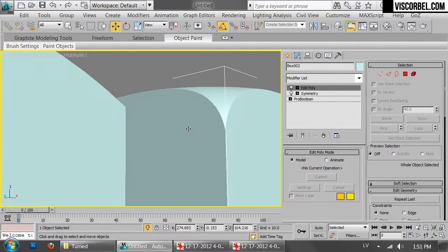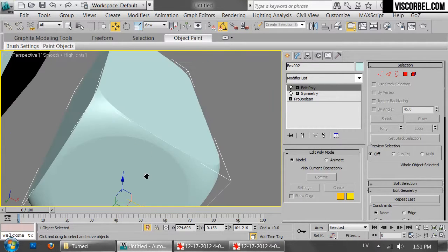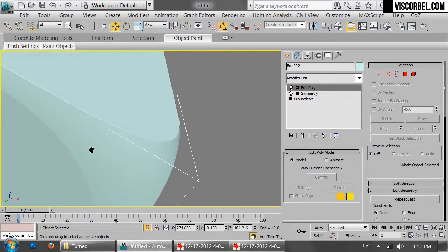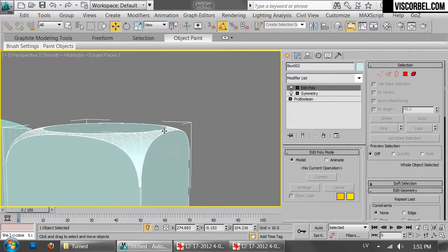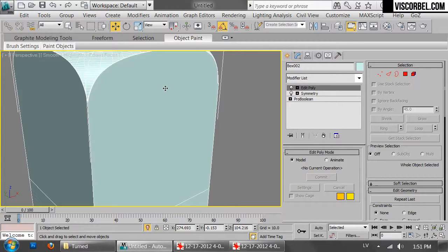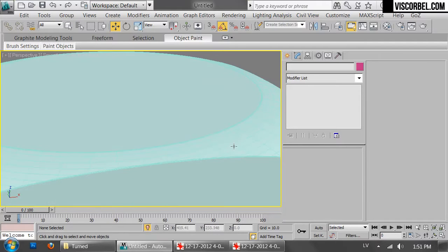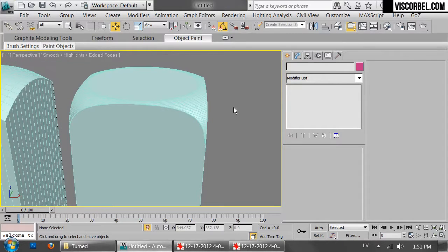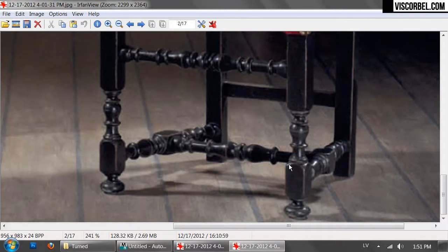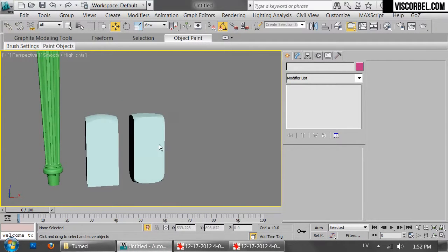But if you use a pretty low value, it might be okay. So yeah, with a very small value, you can do it like this as well. If you want a larger chamfer, you have to go in manually, and that's a bit tricky. Then you would probably use a low resolution profile and edit the resulting mesh manually to add some support edges and stuff like that. But most of the time, these edges are pretty sharp, so this works well, and it's pretty quick as well.